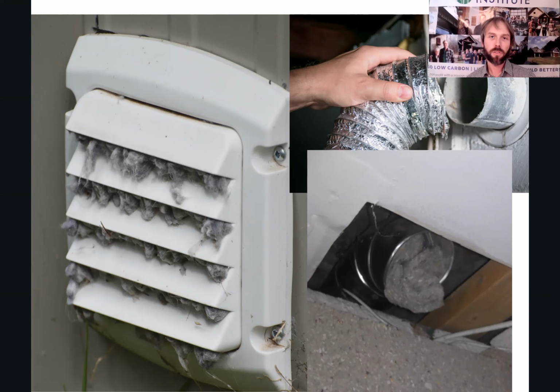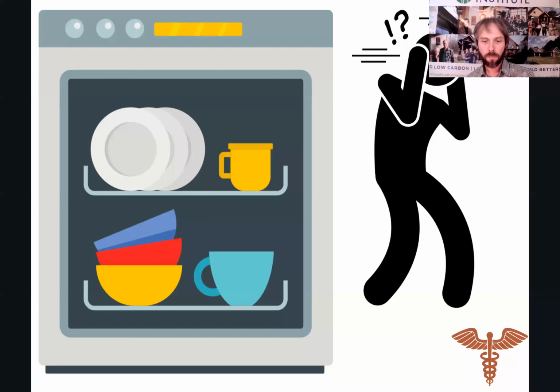So these are very important for energy efficiency, to use a condensing dryer, ideally electric, that just moves the water right down the same pipe that the washer goes, or a heat pump dryer, which is the most energy efficient dryer you can get. A little more expensive, but these are really the way to go. So work with your clients to spec these in. The biggest thing is if the pipe's not there, it's really hard to use a ducted dryer. If there's no pipe, it's going to be expensive to drill it in. So that could be a motivator to make sure they're using condensing or heat pump dryers.